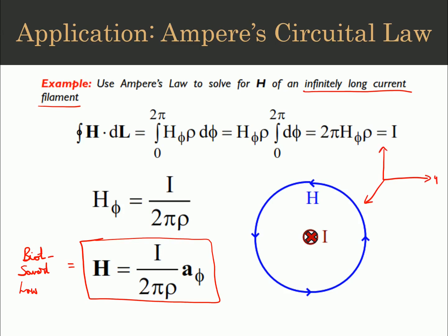If I can redraw it on x, y, and z. So if it is going to positive infinity and negative infinity, and we suppose that the line is along this, where the current is flowing through this infinite line, if this is point 2 where we want to find the magnetic field intensity, we select a portion which was known as the differential length, and we draw an imaginary line showing the distance r from the origin, and this is rho. So we found that the magnetic field intensity was the same as we are getting from Ampere's law.